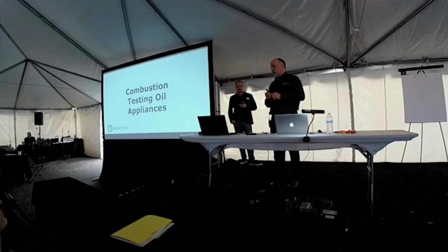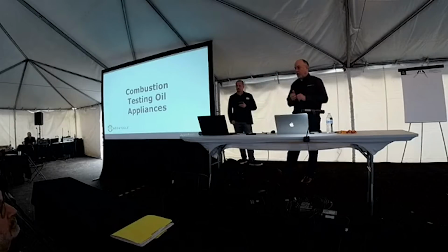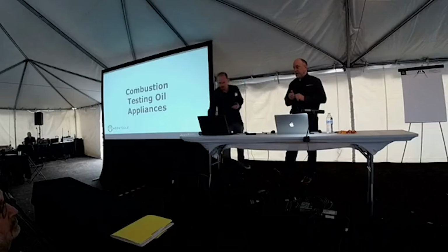Your stack temperature can be anywhere from 90 degrees up to 600 degrees, and it all depends on the appliance. And your O2 could be anywhere as low as, let's say, 30% all the way up to 150%, depending on the appliance. So yeah, it does have a wide range of anticipated outcomes.